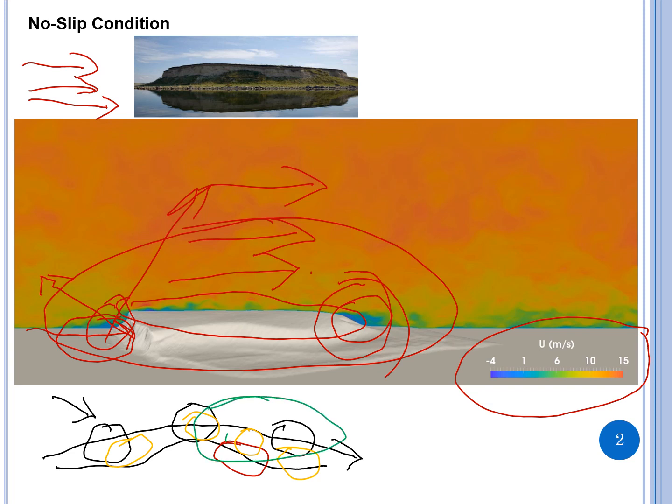That behavior where it loses contact, in terms of fluid mechanics or fluid dynamics, is called flow separation. So whenever there is flow separation, there is going to be some negative pressure in this region, right underneath the area where the flow is separated.